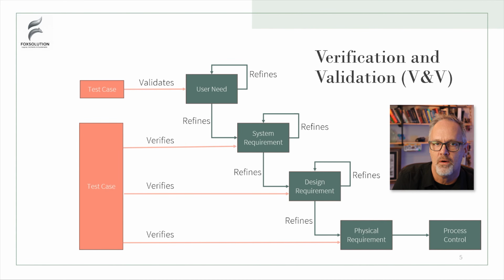Well, so we go build it, and the verification says, okay, the temperature's right, the airflow is right, but at some point in time, we need to bring the user back into the building and say, are they warm? And that's really that validation stage. So usually validation's performed by the end users, and the verification is done by the engineering staff that's developing the design. And so that's really how that deconstruction happens.